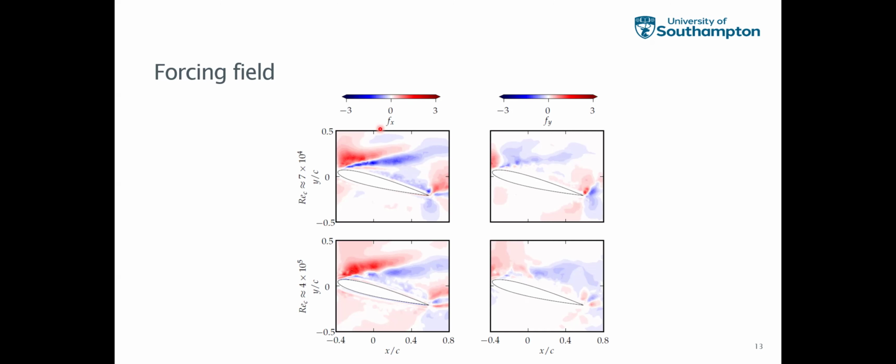Yeah, sounds good. So the second part of the question is the bounds. Now we do set these bounds to be -3 to 3. The setting of the bounds is again something we did think about quite a bit, but in this case the bounds are a hyperparameter. We notice that it needs to be of order 1 if you are scaling all the quantities to 1. We started with -1 and 1, -2 and 2, and then checked -3 and 3. -3 and 3 obtained good convergence and did not blow up the solver. So we decided that -3 and 3 is a good range.